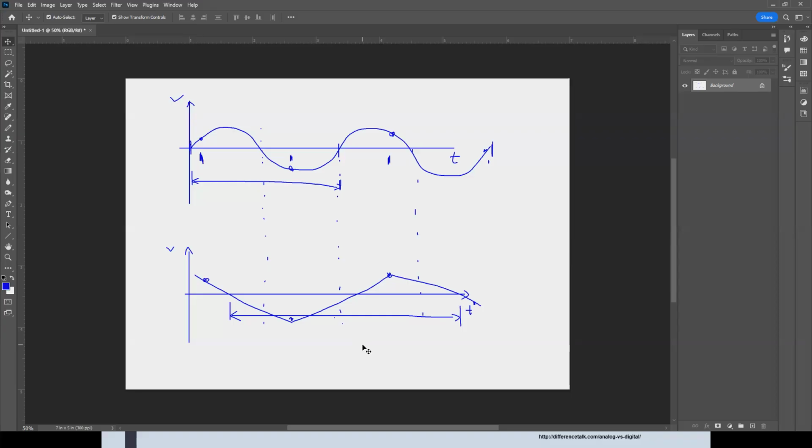It has to do with the sampling frequency of the camera, and then modulating and demodulating and recreating the signal, and the way that the monitor or the TV screen is recreating that scanning, running the dot over the screen with a certain frequency and certain refresh rate, it can create something that's called aliasing.